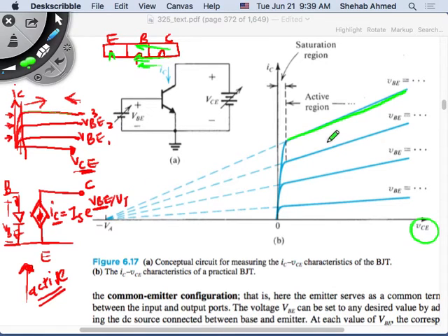If I want to consider early voltage, then it's like when we've pinched in the MOSFET, after you've pinched, and the effective channel length modulation, what was the effect? The effect was increasing current, meaning the slope here versus a straight line. Same thing here. Increases in VCE will do the same thing. I will increase current a little bit.